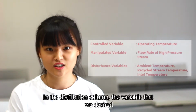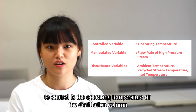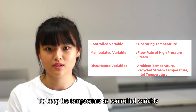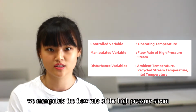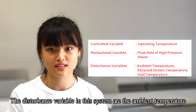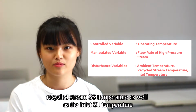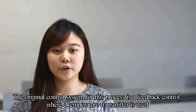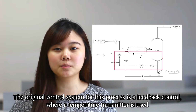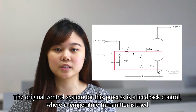In the distillation column, the variable that we desire to control is the operating temperature of the distillation column. To keep the temperature as the control variable, we manipulate the flow rate of the high pressure steam. The disturbance variables in this system are the ambient temperature, recycled stream S8 temperature, as well as the inlet S1 temperature.